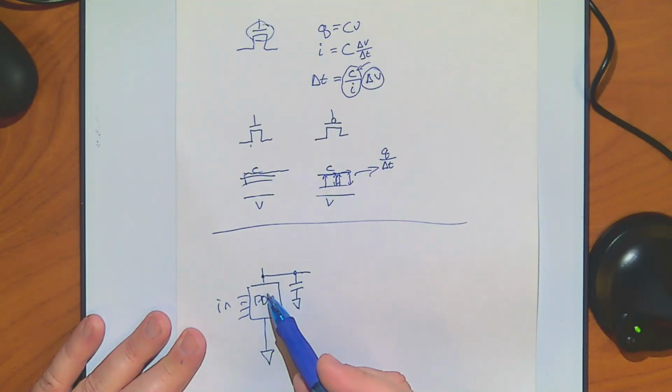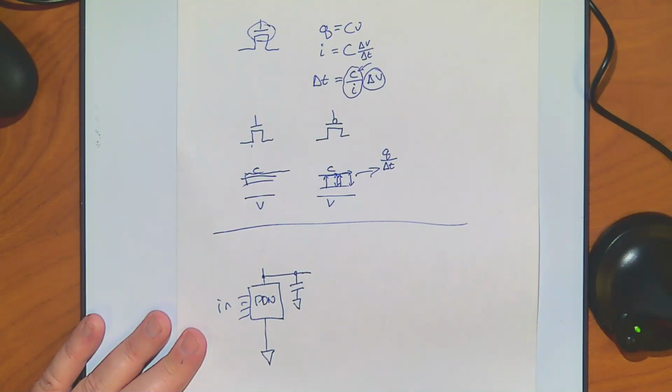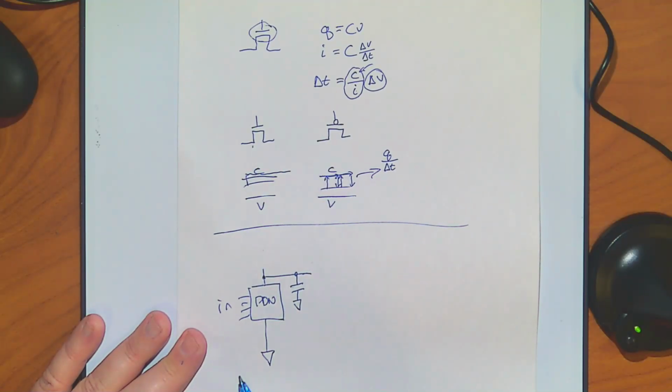And if this network does not turn on, then what's going to happen? This will not be there, and you'll see the charge from the capacitor. Now that capacitor will slowly discharge as it goes out to your system. So you're going to have to refresh this capacitor. This is why I say there's a minimum time, and that time is the time between recharging these. Okay? But that right there is the basic idea. Right? This is the center of it.